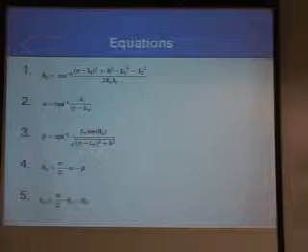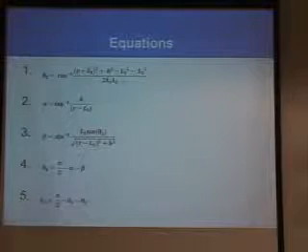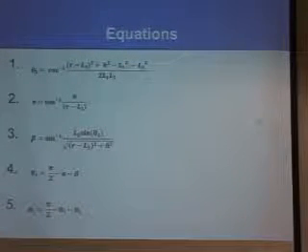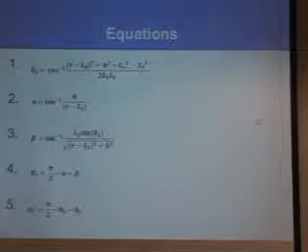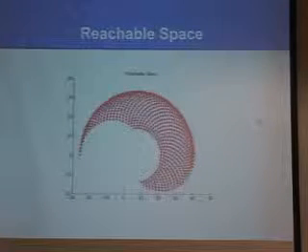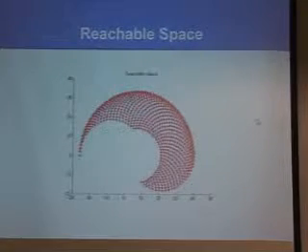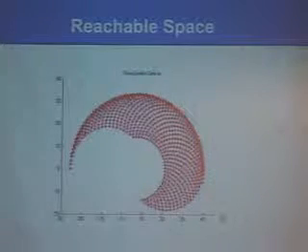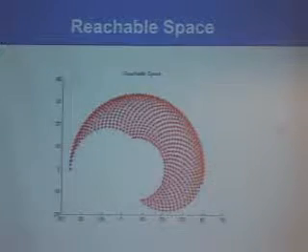The first one is gotten using the cosine rule of a triangle, which is not that difficult. And then 2 more inverse trigonometric relations, and then we're done. We can get all the angles we want. We've plotted the reachable space of the arm in MATLAB in order to know where we could reach, and the values you could see here are in centimeters. The horizontal axis is for radius, and the vertical axis is for height.